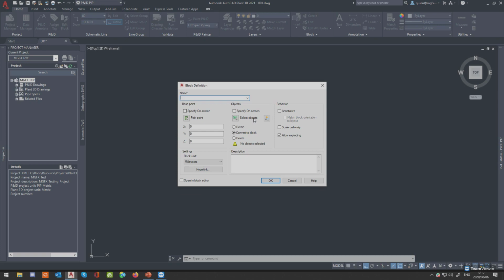So firstly, with our block definition, this would be maybe a super check. This is just a random name I came up with, but now in this section you'll notice I don't have a space, I use an underscore. If you want to save yourself a lot of gray hairs, Plant doesn't really like spaces, so try to use underscores or contract your words together, and you'll save yourself a lot of problems. Some things in Plant do allow spaces, some don't, so it's safer to be safe than sorry. And I'll show you a little trick with naming things in a second.